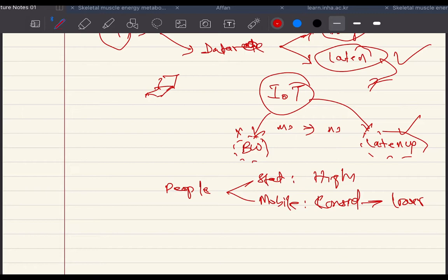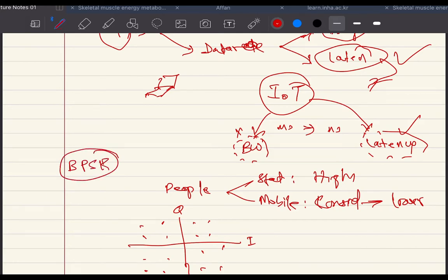To increase the throughput, you need to send more bits per symbol. What does bits per symbol mean? For example, this is your in-phase and this is your quadrature phase. This is kind of your quadrants, and you have to separate your data bits. So previously in the previous lab, you saw that we used BPSK, right? We already saw it in the previous lab, and you are having two states only. You are transmitting 0 or 1.